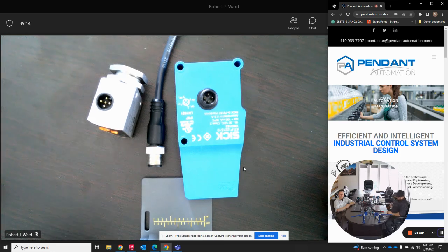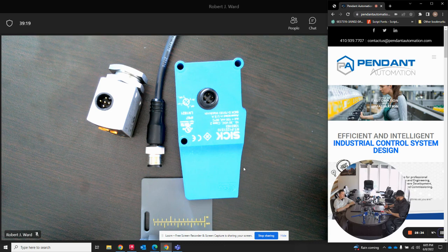So I think, when you think about the big picture of the project, the quick disconnect quickly starts to even the playing field for itself as it pertains to cost. Yep. The ease of replacement, making adjustments. You can take your sensor off. You can swap it out if it goes bad, and the electrician can run extra cabling. So I do think, to your point, though, there is extra cost, but I think that's mostly mitigated by the electrical conveniences as well as the ability to swap a photo eye in the field without calling a high-priced electrician to your job site.